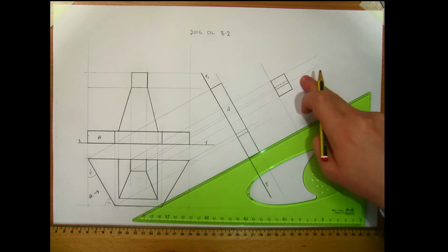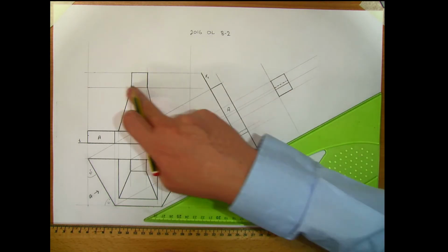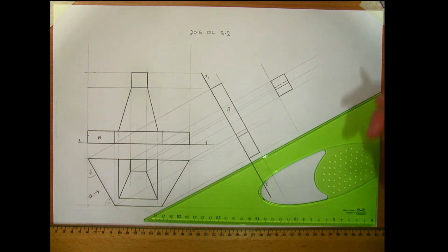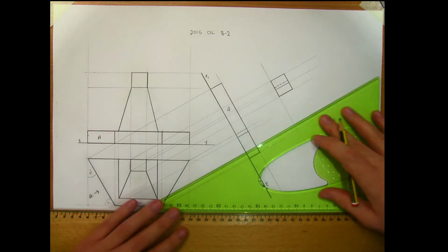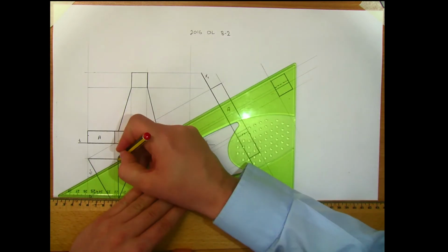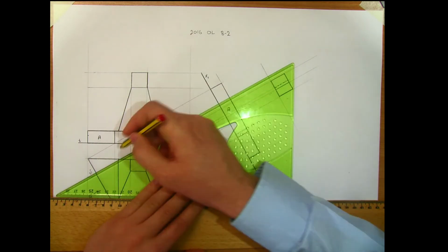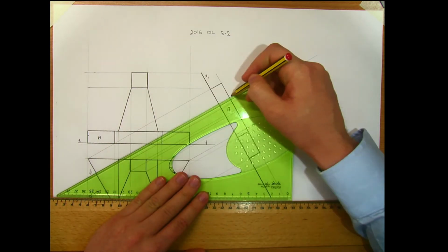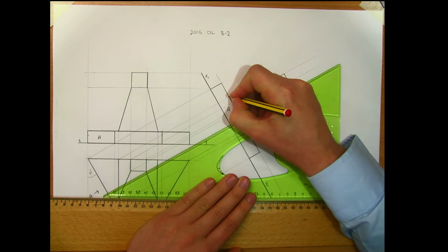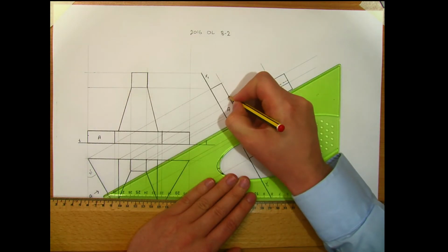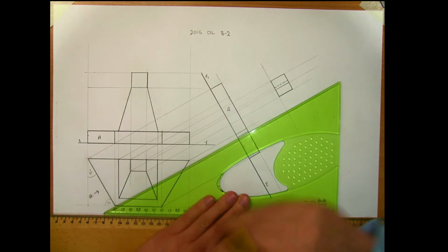So we've got the very top of it done, and we've got the base of it done. Now we need to do this bit here in the middle where it spreads out. So I'm going to take each one of these in turn, one at a time. I'm going to take this corner here, which is this corner up here. So projecting this line up along this way. A point here on the top surface, so it's on that surface there. So same height up off the ground, off the XY line as it is over here.